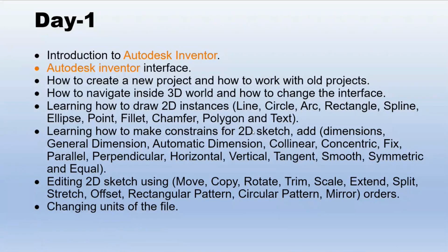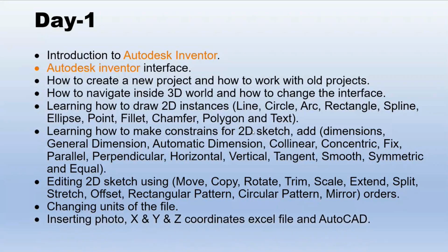After that, we will learn how to change the units of the file. If you would like to deal with the units in inches or centimeters or meters or millimeters, or the weight in kilograms or pounds, you can change the units of your document. We will also see how to insert a photo into your sketch, how you can import an Excel file including the locations of points in X, Y and Z, and how we can import an AutoCAD drawing.